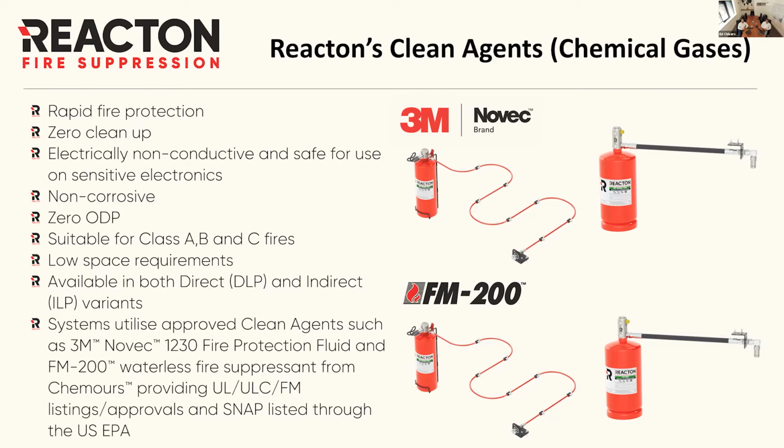So most of the people are well versed in what clean agents are and how they work, but we've got a nice run through on the side here about the rapid fire protection. Typically they're designed for 6 to 10 seconds for the indirect to discharge, zero cleanup, electrically non-conductive, ideal for sensitive electronics, non-corrosive, zero ozone depletion potential, covers A, B and C fire classifications, low space requirements compared to other solutions.